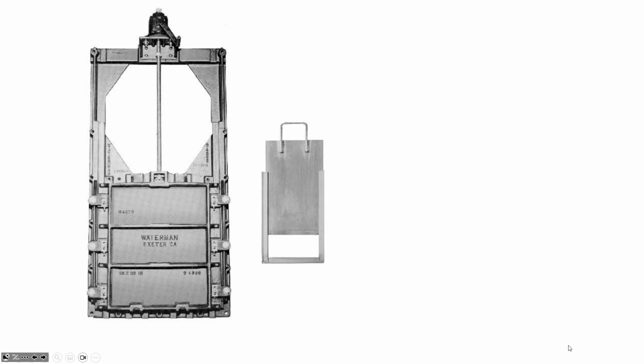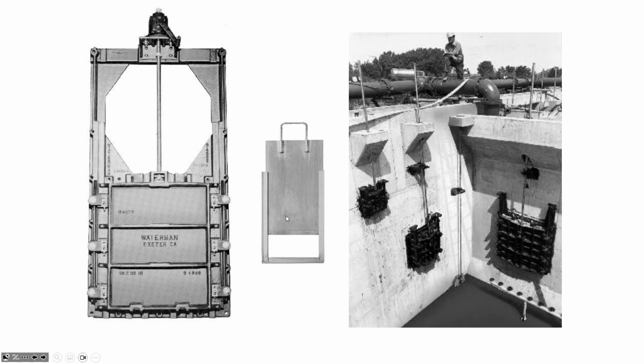And gates can be far more sophisticated and have a lot more mass to them. But they follow the same principles, and that is that there is pressure pushing on the gate and forcing it closed up against the frame. And so there's going to be a certain amount of force that you have to lift up on the frame just by virtue of the mass and the accompanying weight of the plate, but then also the pressure of the water pressing against the gate as well.